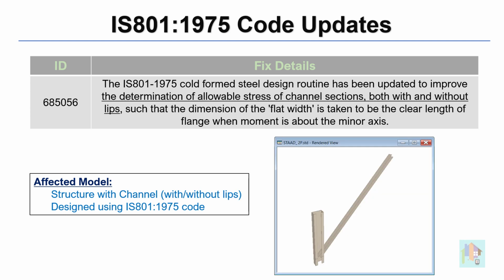For IS 801 cold form section design, there is one update. The design routine has been updated to improve the determination of allowable stress of channels with and without lips when moment is about the minor axis.